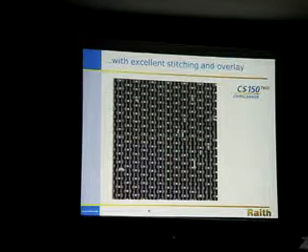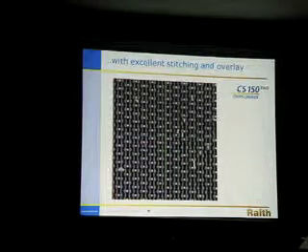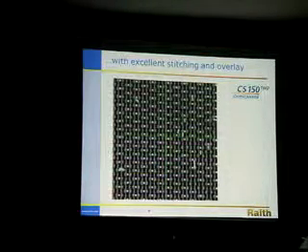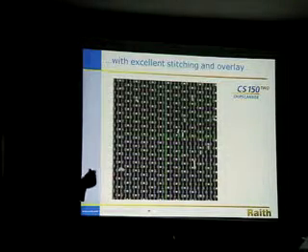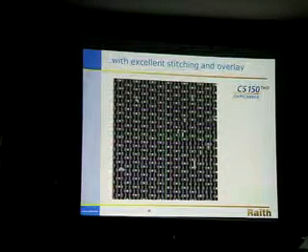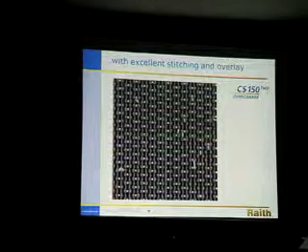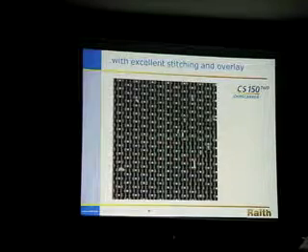Then our customers go down to metal layer 2 and do the same thing all over again. Since they have the laser interferometer stage, they have overlay registration between one layer of SEM images and another underlying layer of SEM images. This is a very demanding but important task. Our customers are using this Wraith 152 system to look at obsolete chips, to check for counterfeiting, and also for other defense purposes at technologies below 64 nanometers.